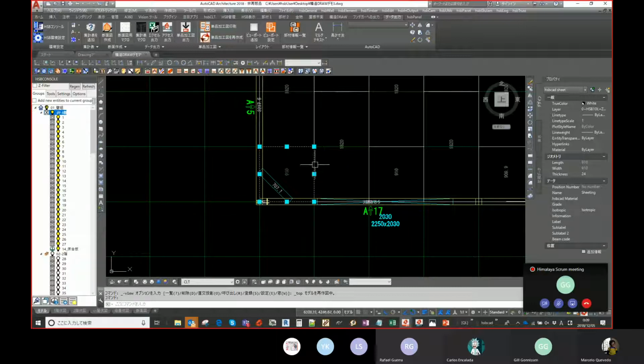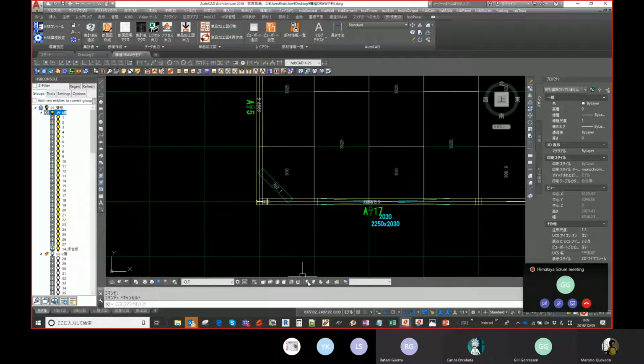Are there specific rules in the sheeting? No, they just have to sit on the studs. But the studs are already drawn? Yes, they are drawn. Or even the supporting studs for nailing, no? Where can I have the joints? Can I have the joints in all the beams, or are some beams excluded? Some beams are excluded that have a dimension which is too narrow. And around openings, do you start at the opening?